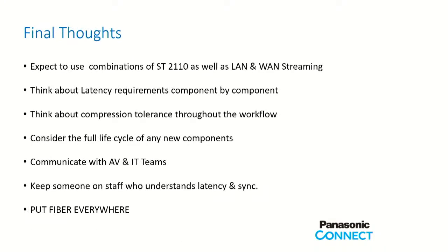And final thought. So expect to use a combination of ST2110 LAN and WAN streaming. So both are possible. So they wanted to bring in ST2110 and they wanted to bring out the streaming output of the Kairos. And the latency requirement: whenever you have a compression like NDI or SRT, then you have latency in the system. So please be aware of it.